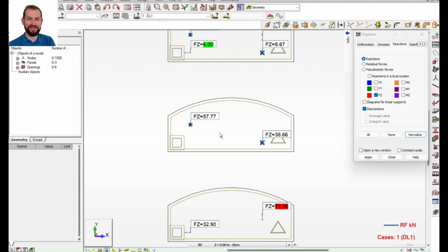So essentially that was the self weight only. We can go up here to look at the load with our lifting coefficient. So our lifting coefficient was 1.2. So obviously 71.16 times 1.2 is 85.39, which is what we have here. And then for the ULS condition, there was another 1.2 on top of that, which was 102.47, which is what we have on top of this.